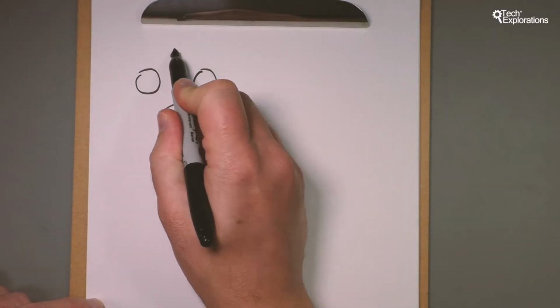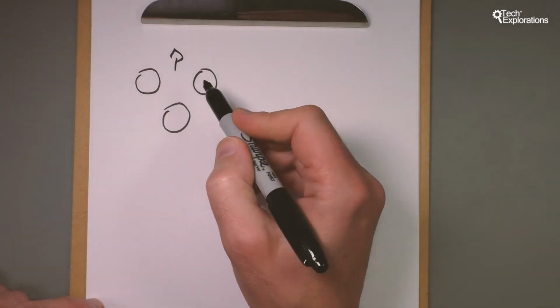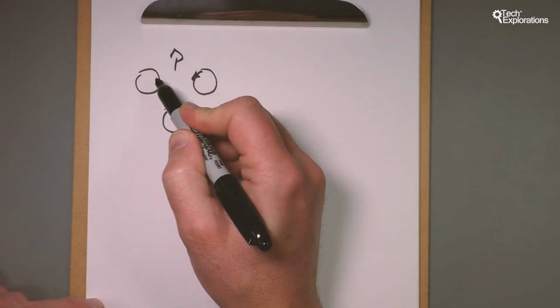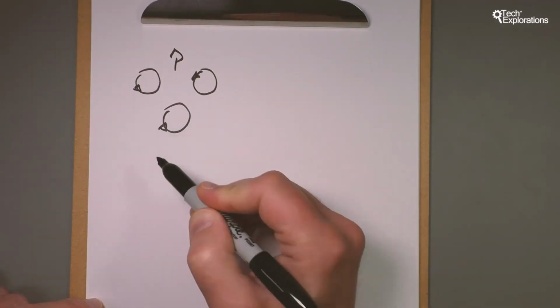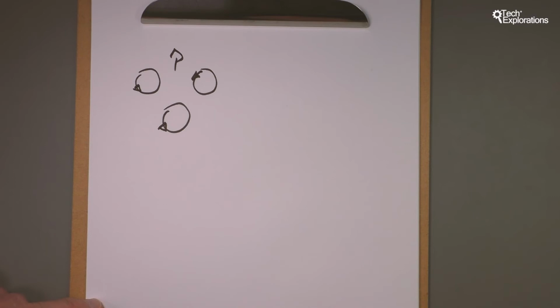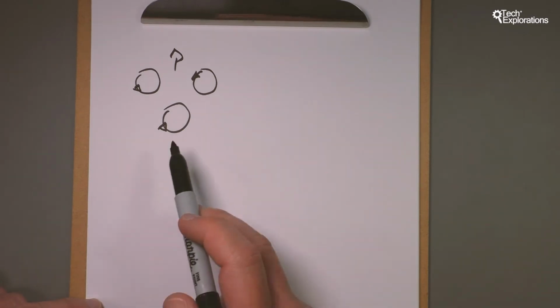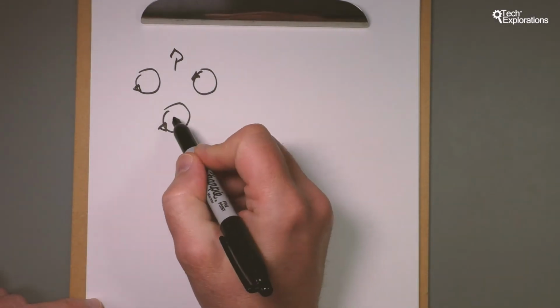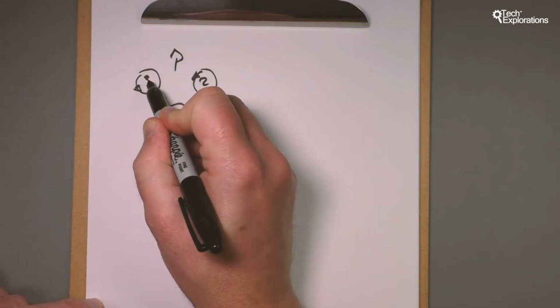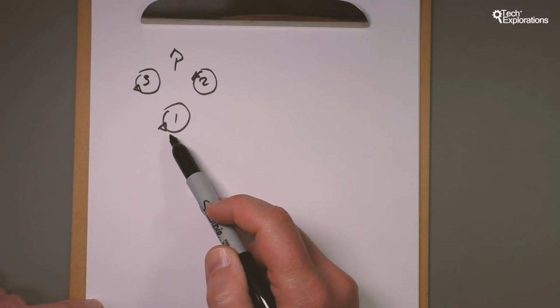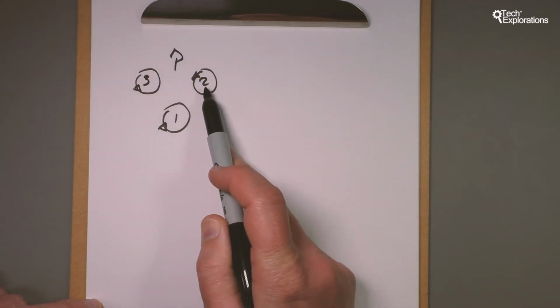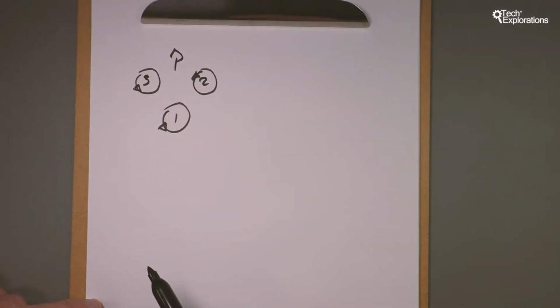And this is the front, this is how they're going forwards, and then you need to have a balanced mode of rotation for the propellers like this. So propeller number 1 is this, 2 and 3. Propeller number 1 will move in a counterclockwise motion, propeller 2 and propeller 3 in a clockwise motion.